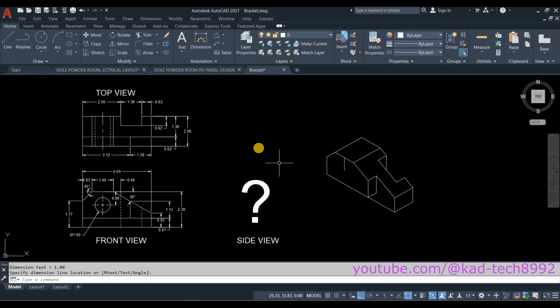It's 1.00. So again, let's go back to isometric snap. Type ellipse, enter, isocircle, click on the endpoint, type D for the diameter, and then type 1 or 1.00. Now, remove this line. All done. It's all correct now.